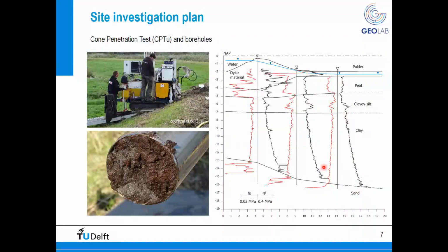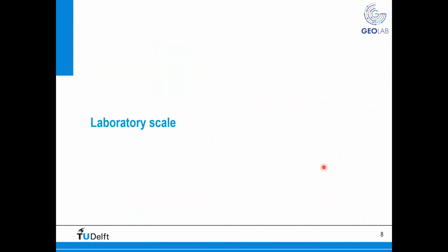Now, after having performed the field investigation, so we were able to clarify what was the layering of our subsoil, we basically move our attention to the laboratory scale and perform a characterization of this material, both in terms of index properties, compression behavior, and also shearing behavior.